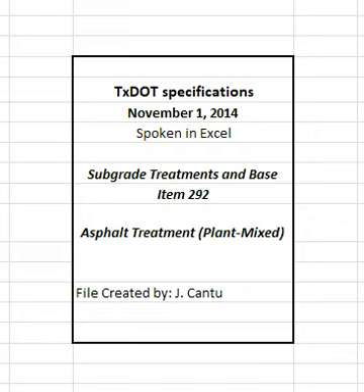5. Measurement. Asphalt treated base will be measured by the ton as a composite mixture of asphalt, aggregate, RAP, and additives noted on the plans and approved. Measurement will be made using scales meeting the requirements of item 520, weighing and measuring equipment.